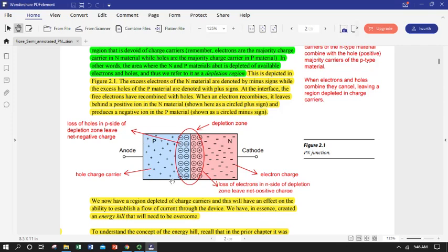So this started out as a single crystal of silicon, and then somebody put this in a furnace and put a bunch of phosphorus, say, containing material over on this side that provides that pentavalent dopant that has that extra electron. So it's going to make a bunch of electron majority charge carriers, and it diffuses in over time and makes an N-type material. At the same time, in the same furnace, we have maybe some boron over on this side, and we let it diffuse into the intrinsic